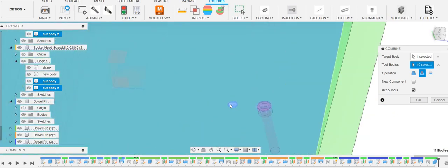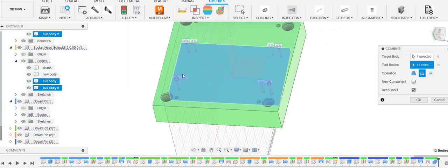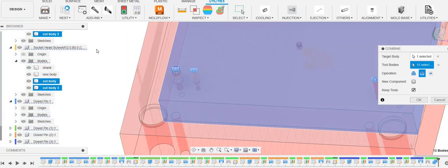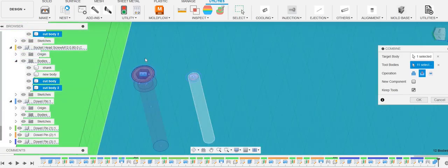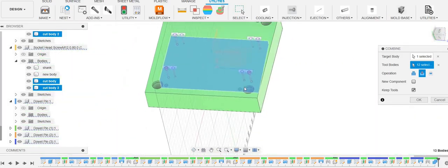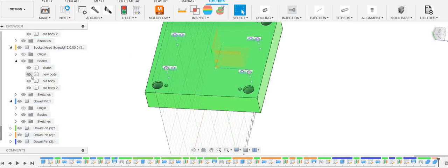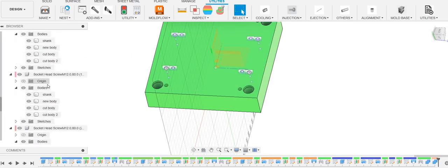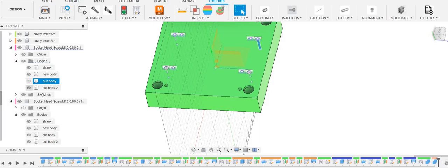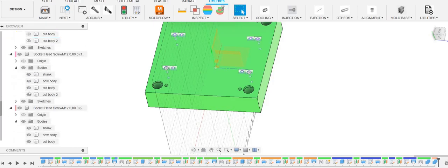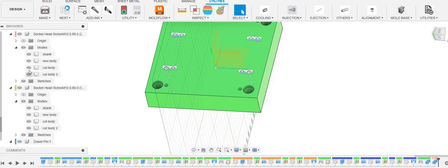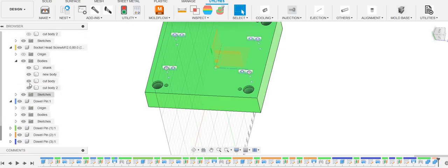Because if you want to talk about dowel pins, the screw aligns the component in the Z direction. The work of the dowel pins is to align the components in both the X and the Y direction, so you have proper alignment at the end of the day.